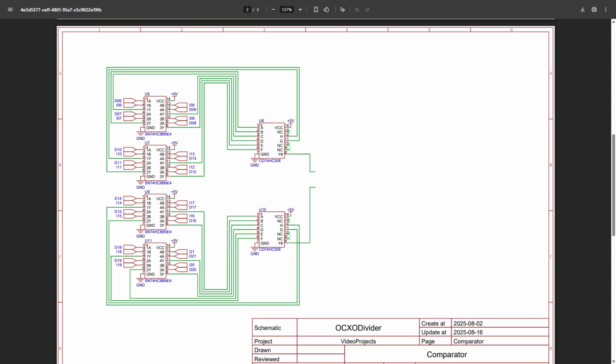The solution is to set the inverse of the number we want in the microswitches. When all bits of the number on the counter and the microswitches are opposite, the XORs will output a 1, and the NAND gate will output a 0. And the same is done in U10 but using the bits from U9 and U11.